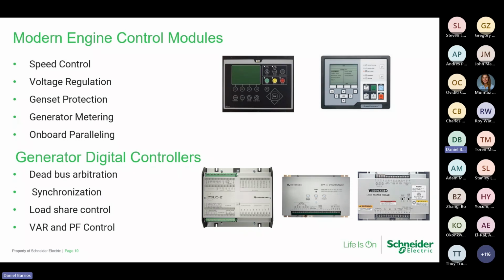A comment to you is that if you are reworking a system and you have existing generators, please get as much information as you can from the field. What are the control panels? What are the voltage regulators? What are the governor systems? It will help us coordinate with you folks.